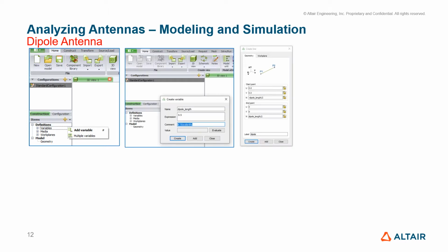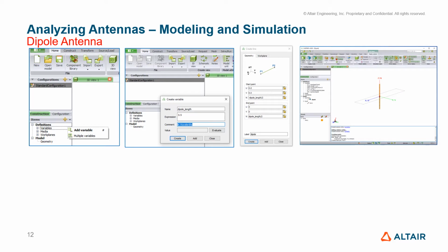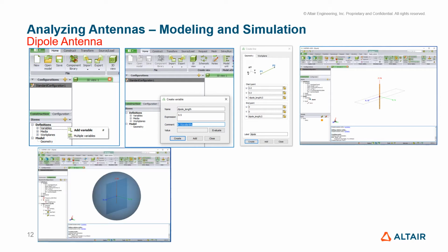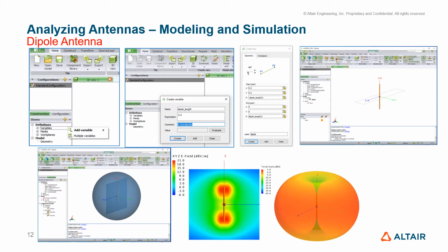And then, of course, you can define the dipole length, whichever you want, and discretize it with an appropriate number of segments. Then you can define the quantities you want to compute, the radiation pattern, the near fields, etc. And then the tool will compute those quantities for you. And of course, you can then compare your simulated current distribution on the dipole, this is a lambda by 2 dipole, with the one analytically computed in the last slide.